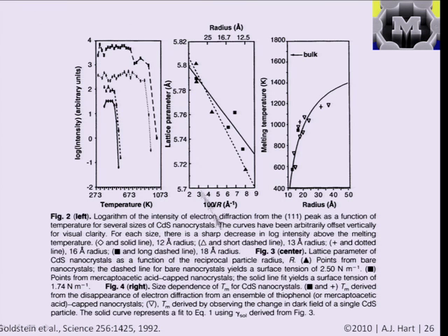And they study, for example, the question is, well, how do you determine that the particle has melted? Well, in the case of going from a solid to a liquid, if you're looking at, for example, the diffraction pattern, then the strong diffraction peaks that correspond to the order of the lattice would go away when the particle goes from solid to liquid. So if you plot, for example, in arbitrary but the same units for each particle size, the intensity of a certain diffraction peak versus temperature, then you'll see that when that intensity drops way down, basically when the atoms are no longer ordered to cause the diffraction of electrons, then the particle has melted.